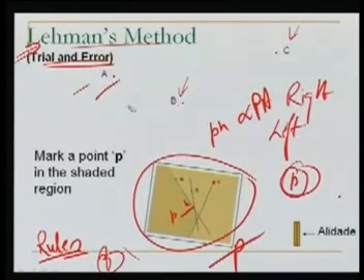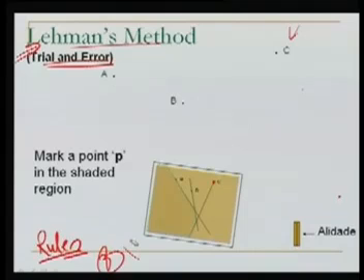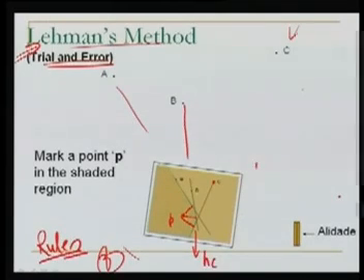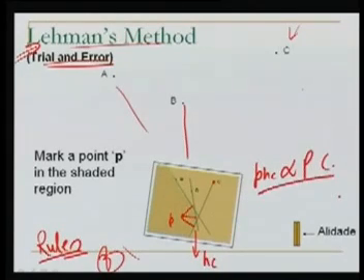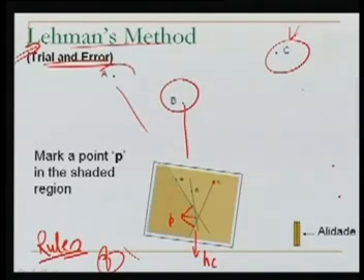We need not measure it in order to solve this method, just an approximate idea of this. So the point P will be in ratio: the distance of this should be proportional to the distance here from the resector to B, and again proportional to the distance here from the resector to C. This distance P, and let's say this is H C. So P H C should be proportional to P C. So we have to find the distances in these ratios, in the ratio of the distance of the table from the points there on the ground.